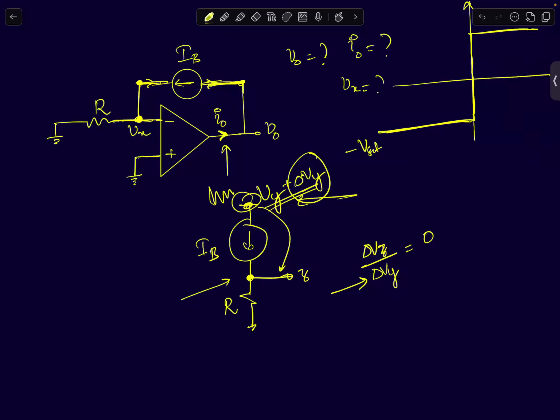Okay, so now keep this in mind and come back to this circuit. Do you think there is any feedback in the circuit? Even if I change this output node voltage, there is no feedback, because when you say there is a feedback action, when your output is changing, this node should also change.